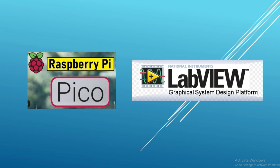Raspberry Pi's Pico is a microcontroller board developed by the Raspberry Pi Foundation, which was released in January of 2021, and is designed to be an affordable, easy-to-use platform for electronics projects and learning. The Pico is based on the RP2040 microcontroller chip, and it has a dual-core ARM Cortex processor running at 133 megahertz. It has 264 kilobytes of RAM, 2 megabytes of flash memory, and 26 multifunction general-purpose I/O